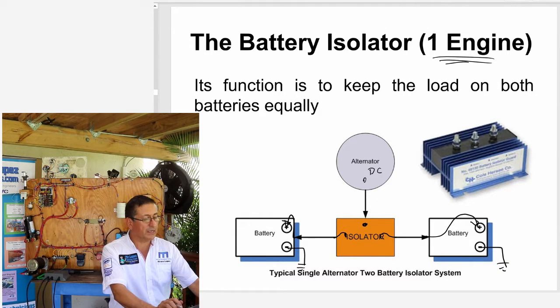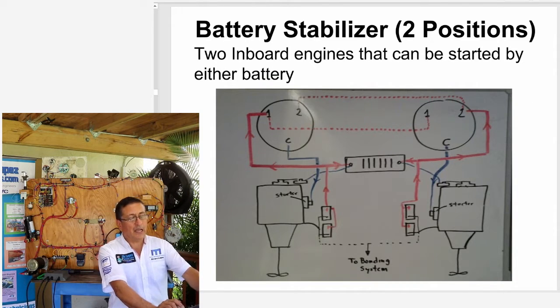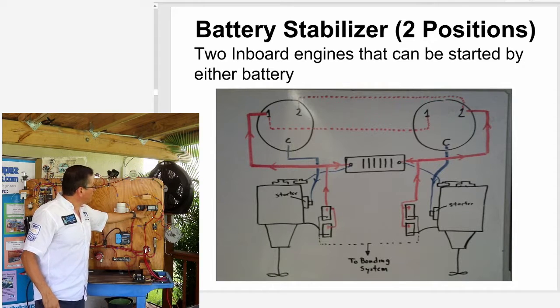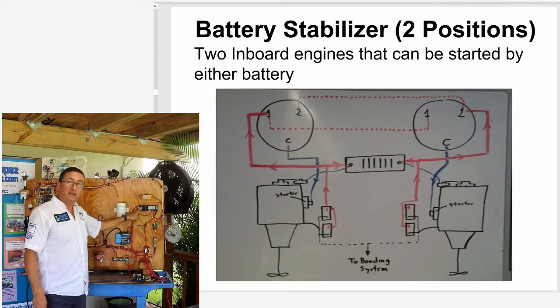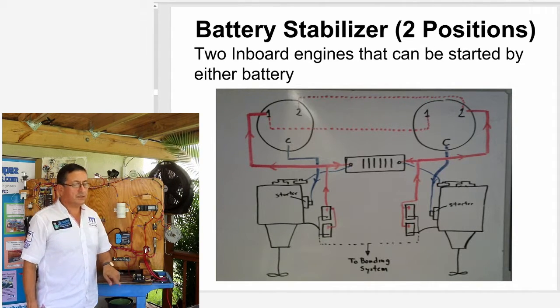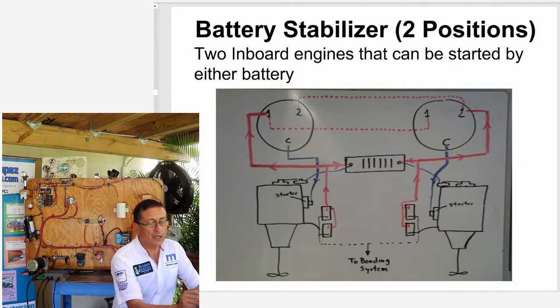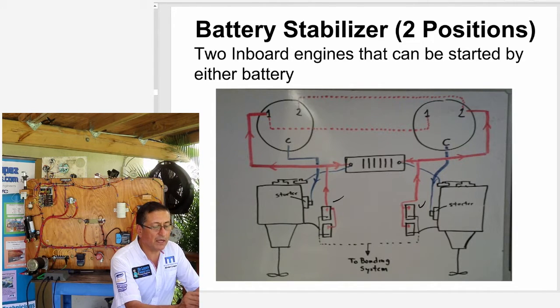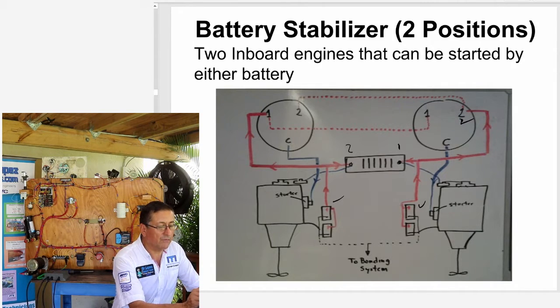I have another ACR, for example, this one. This is excellent. I love this picture. This battery isolator or ACR is exactly like the ACR that we have in the picture. Let me follow the diagram. I have one battery bank, I have another battery bank. The positive of this battery bank enters in position number 1, and the positive of the second battery enters in position number 2, and from position number 1, I connect to the position of this ACR, and from this position, I connect to the other position in the ACR. And internally, I connect position 1 with position 1 and position 2 with position 2. What is the advantage of that design?